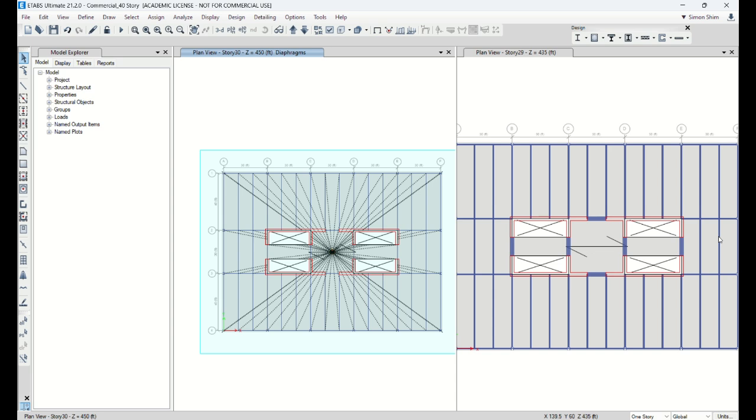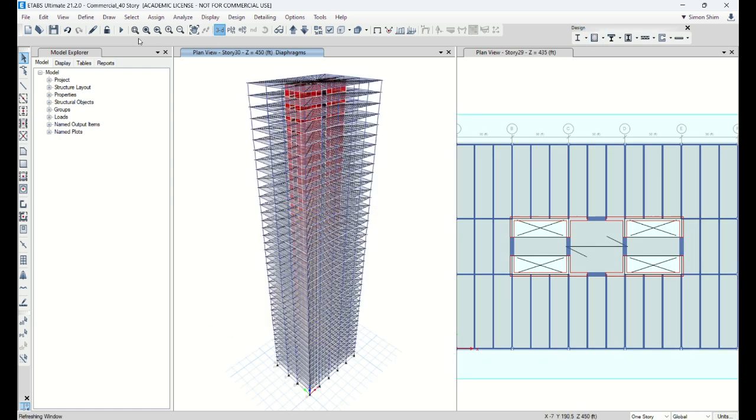Eventually, we tell all these nodes to work like a rigid diaphragm, which works as rigid body motion under any lateral load. So this actually moves together in X and Y and twist torsion, but no interior displacement. So this is the minimum you need to set and run it.